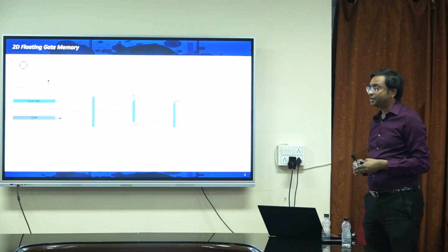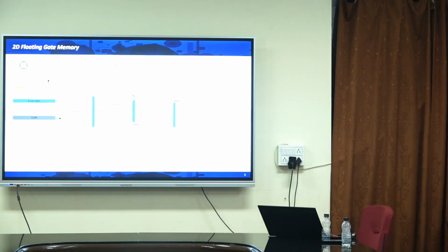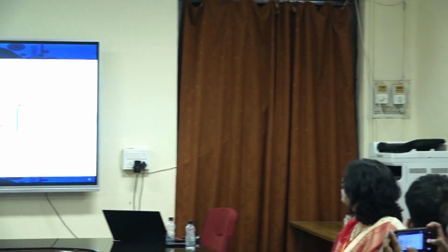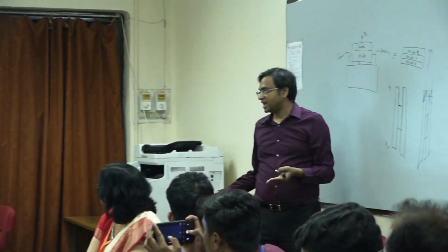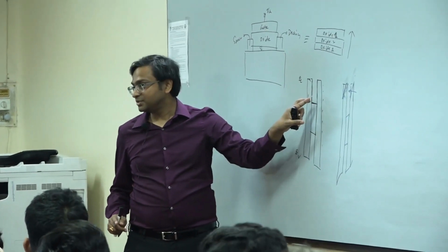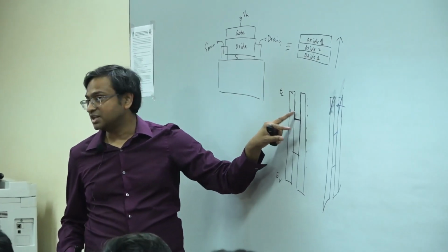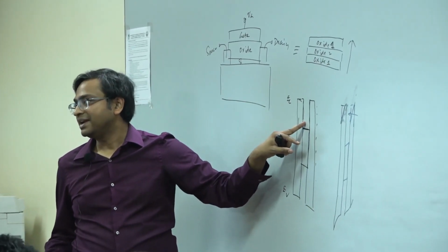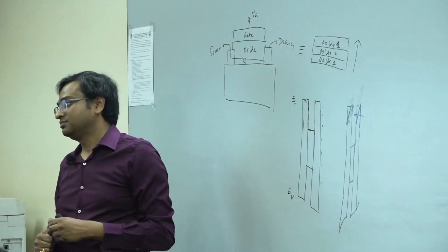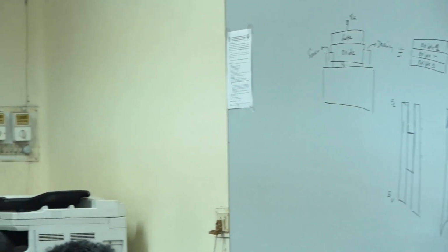So it all depends upon how long you want to store, because even if the charges are here, they can actually go out because of the quantum mechanical tunneling effect. So based on the thickness of this oxide and the dielectric constant, it will determine whether the charges will stay here for 10 years, 10 days, or forever. So it all depends upon the requirement.